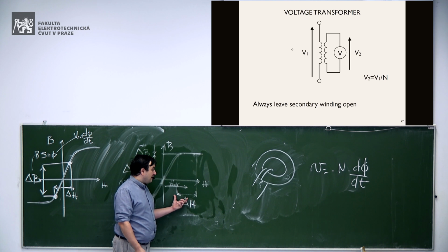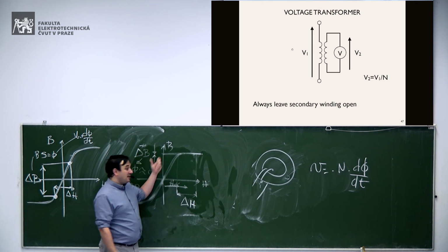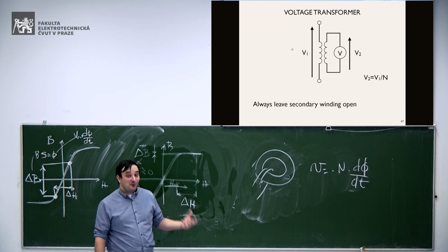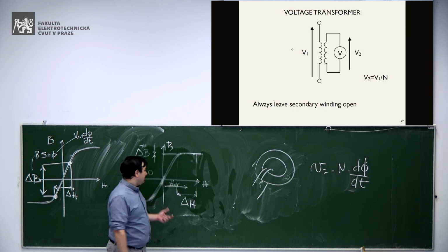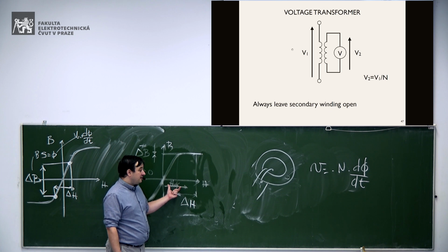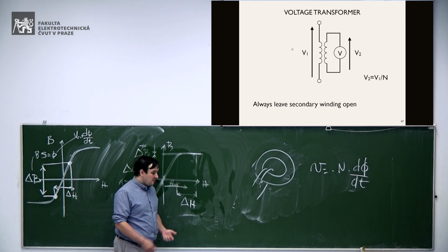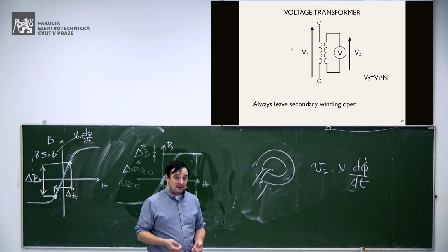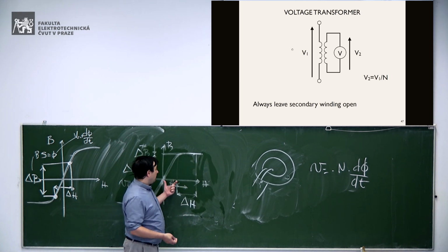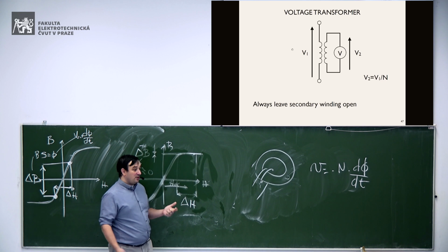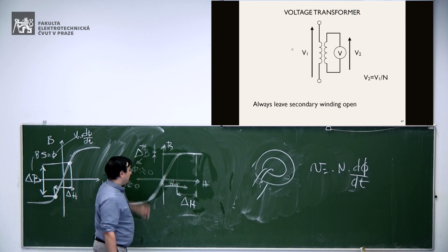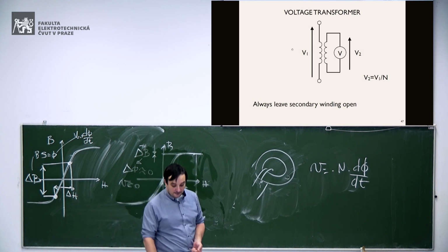The current in the current transformer would still change, create a time variation of magnetic field, but then you get nothing at the output, like if there was no change of magnetic field. And that's what somebody tries to do. They will add a DC field to the current transformer using a permanent magnet, a very strong permanent magnet. With this permanent magnet, they bring the core into saturation, and therefore they don't pay energy because it seems there is no signal at the output of the transformer. Okay?